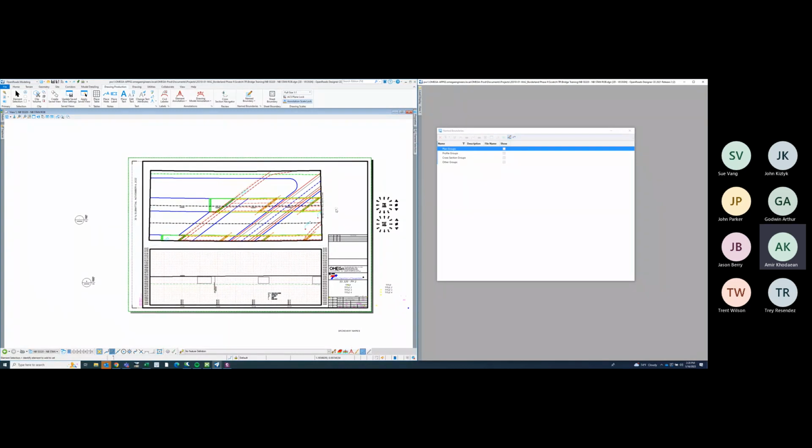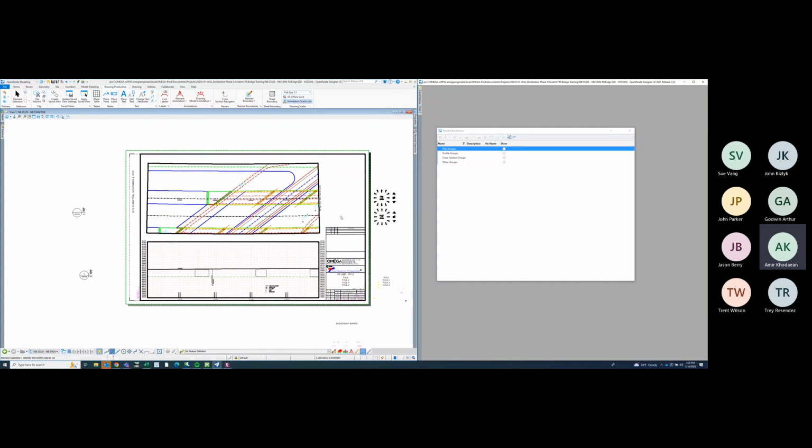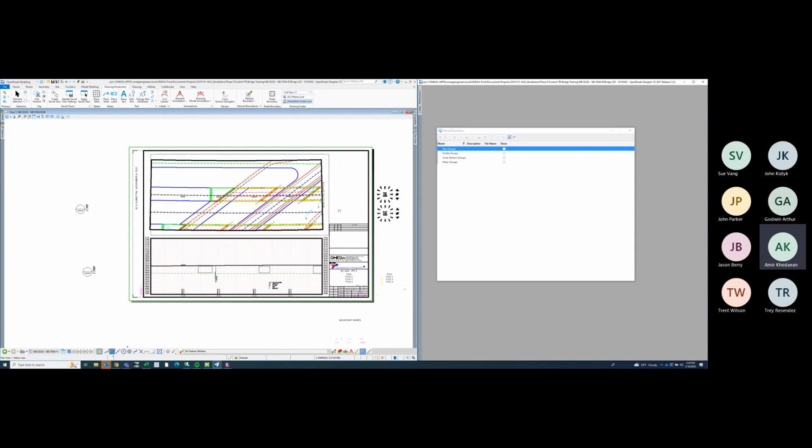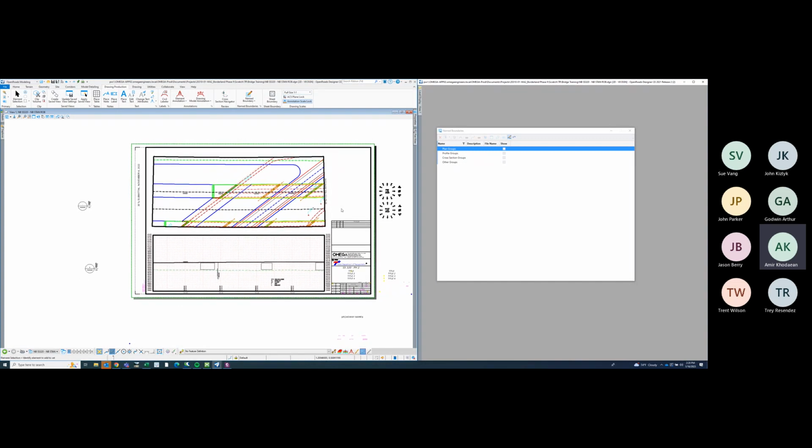If you draw just one profile in your motif which covers the whole length of the bridge, then by whatever match line you define, it starts doing piece by piece of each one into the sheet model. So you don't have to worry about changing everything inside every single one. You just have to update the motif file profile, and automatically all the sheets would update accordingly.